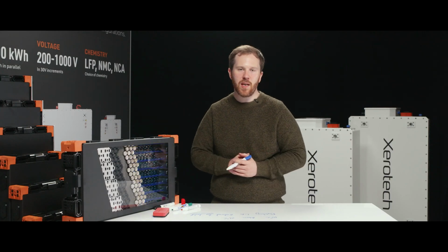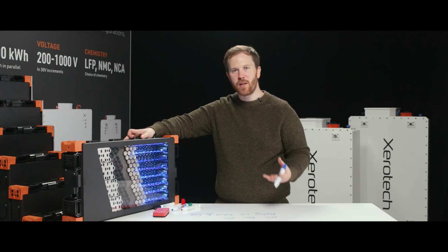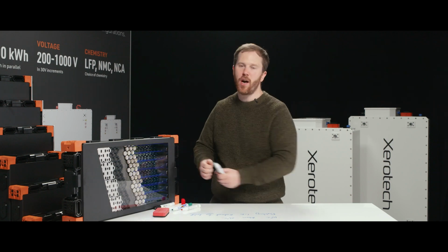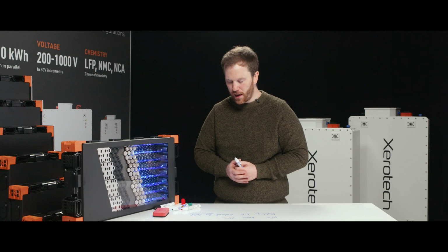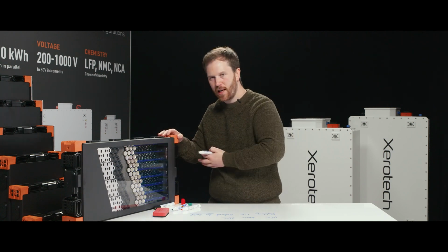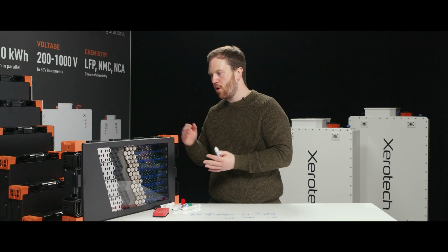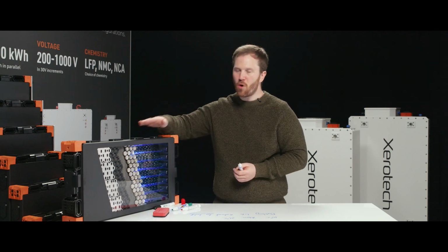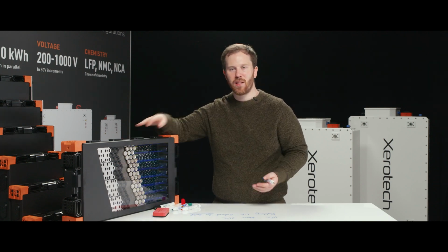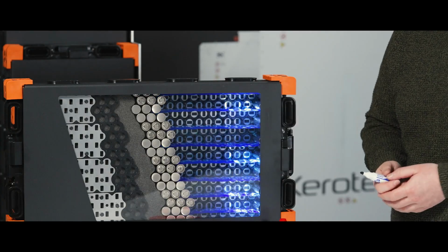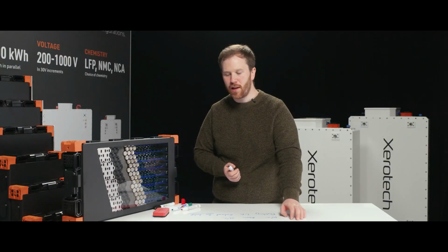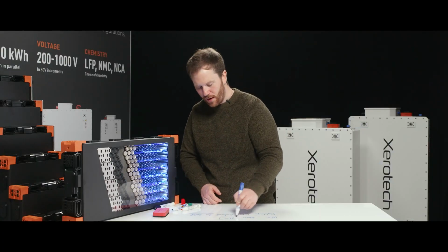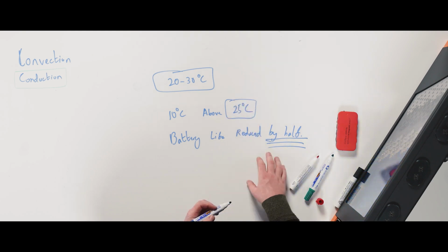So even if you don't need your battery to be actively cooled down, for example, you're discharging it very aggressively and you want to get maximum power out of it, that will generate a lot of heat, which has to be taken out of the battery so it doesn't have to shut down or be derated. Even in more mild applications, so batteries that have to operate for 8 hours a day or 10 hours or even 4 or 5 hours, it's really good to have thermal management, because if you can keep your battery at a nominal temperature, it's going to last a lot longer than a battery that has uncontrolled temperature.